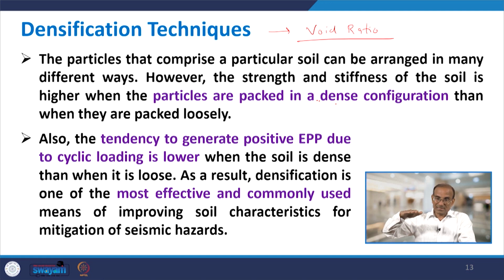So, if you densify, in fact even when foundations are constructed, a bed of PCC, which is called plain cement concrete, is created before and it is compacted by using handheld hammers, compacted by striking so many times. So, this compaction is also one type of densification, where you densify the soil to increase its strength, because the voids will be reduced.